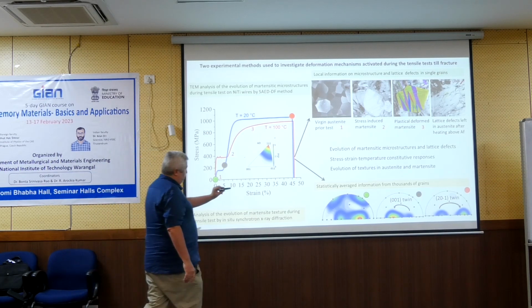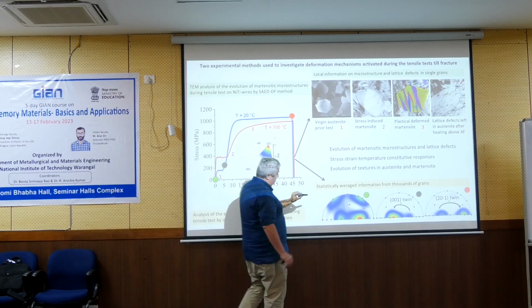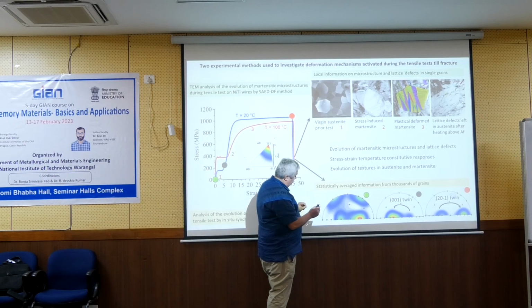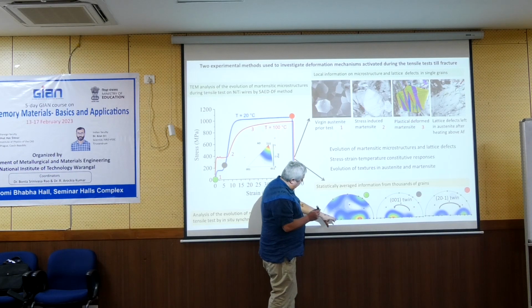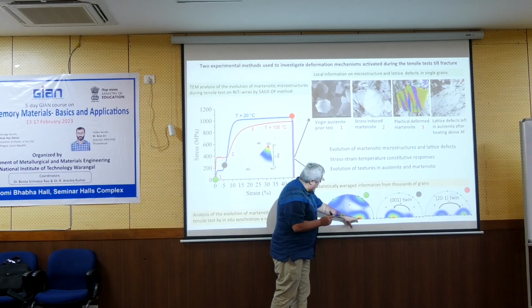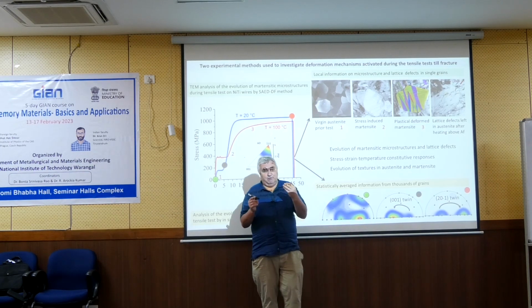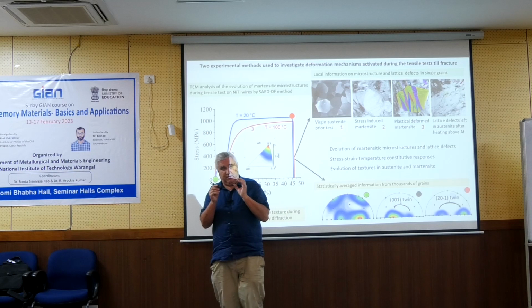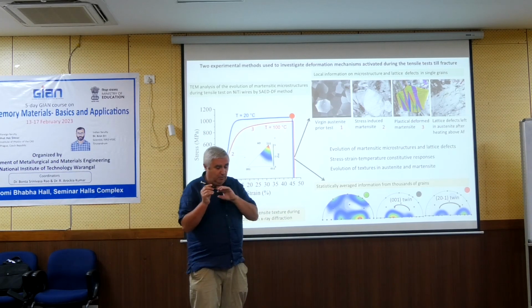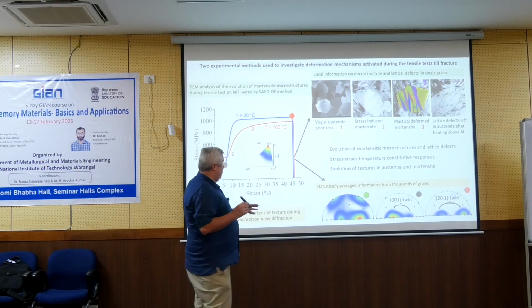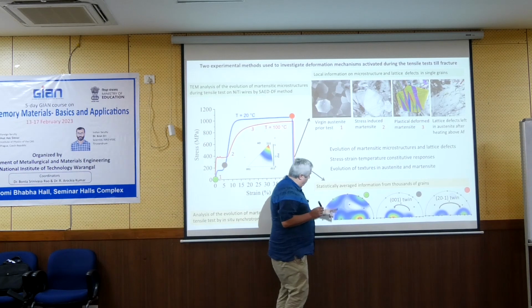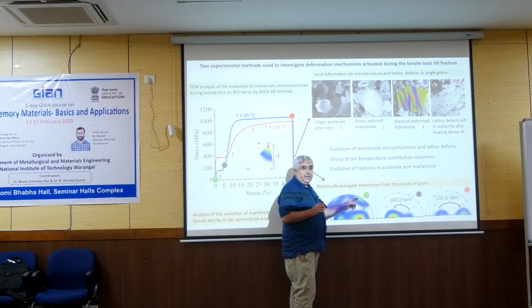And this is the result of the texture experiment, which actually says that the crystal is oriented, some variants are oriented here, some variants are oriented here, some here, and some here. So there are like 4 poles. So if the martensite is obtained by just cooling, there are these four poles, okay?